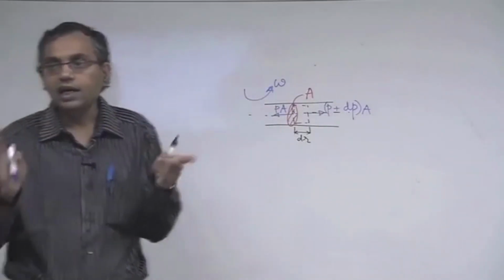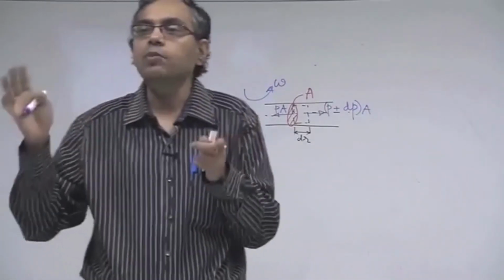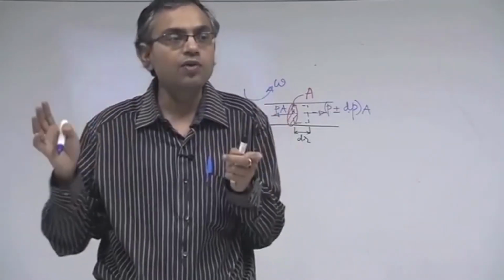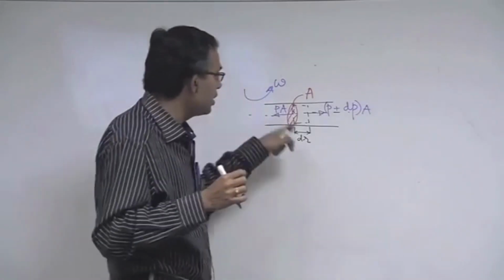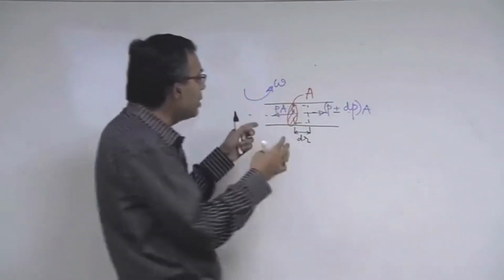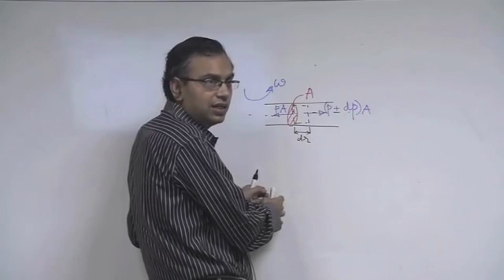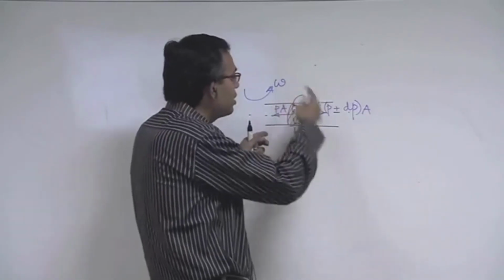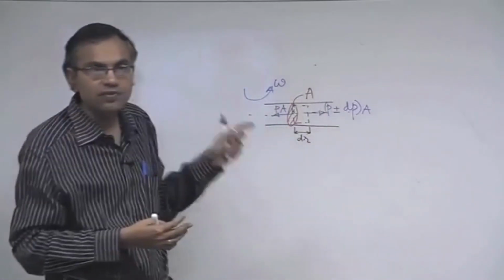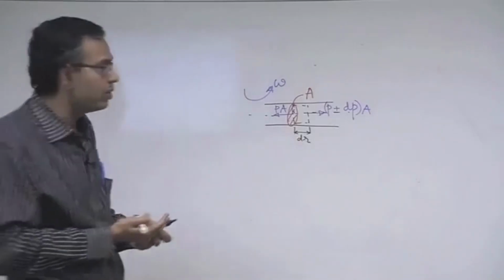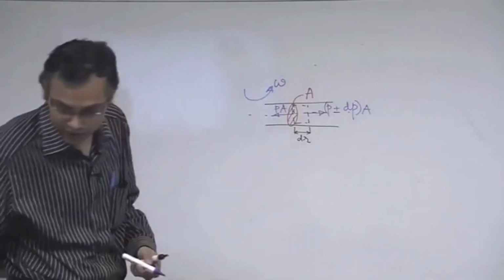However, if you are writing resultant force equal to 0, it is as good as writing resultant force plus minus m into acceleration equal to 0. That minus m into acceleration is the inertial force, and here the acceleration is because of the centripetal, depends on how you interpret it. It is a centripetal acceleration if you are talking in terms of acceleration. If you are talking in terms of inertial pseudo force by being located on the rotational reference frame, then that is manifested in the form of centrifugal force. So let us choose that second path. Yes, yes, pressure is inwards, right.